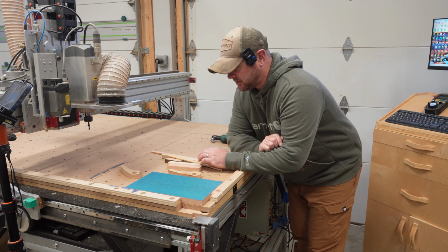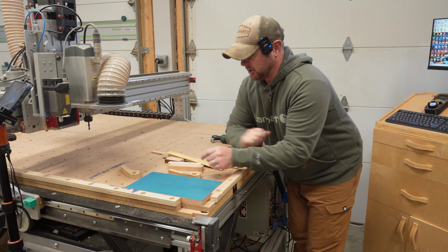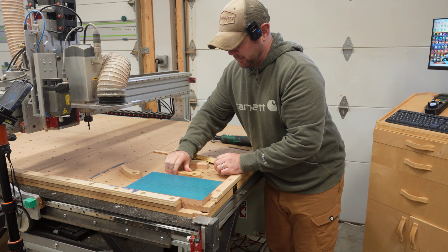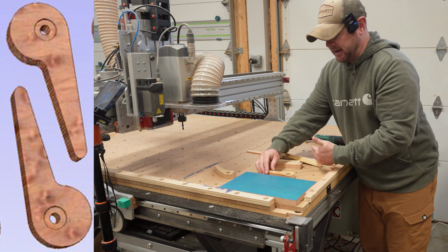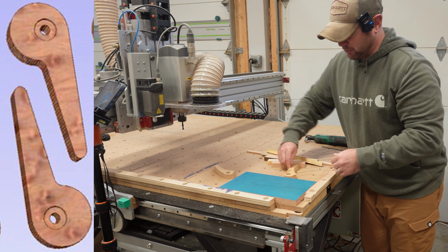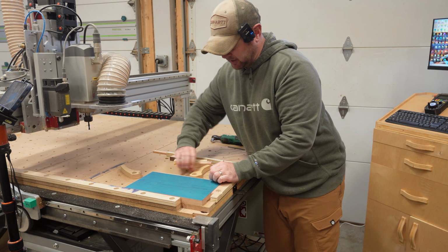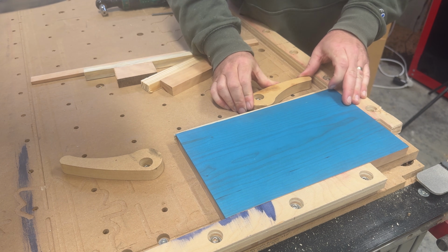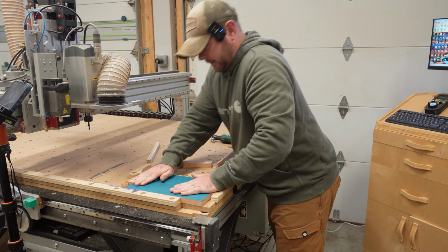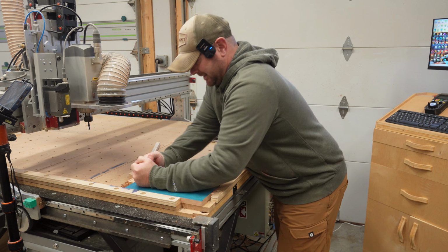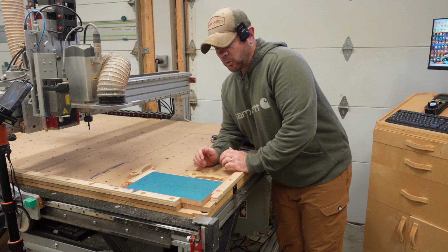So I recommend you always have a ton of thin scraps handy if you're going to use this work holding method, because you're always going to need pieces to shim. So these are eccentric knobs, which means they get slightly bigger as the knob progresses, so it can tighten down against this workpiece. But you may need to put something in to give it enough to clamp to. So that looks perfect right there. All right, make sure it's flat against your CNC top. That's not going anywhere. That's one work holding method.